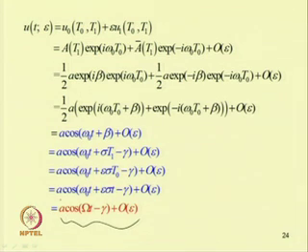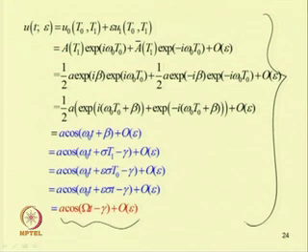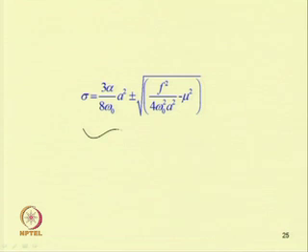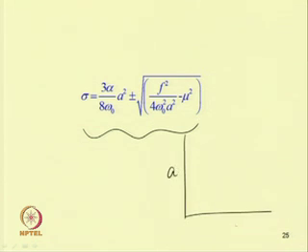So, u equal to A cos(omega t minus gamma), that means the system will oscillate with the frequency of external excitation in case of the non-resonant condition. So, this is what we have discussed for a system if it is weakly nonlinear, and this is the relation between the detuning parameter and response amplitude. By plotting the response amplitude versus detuning parameter sigma,